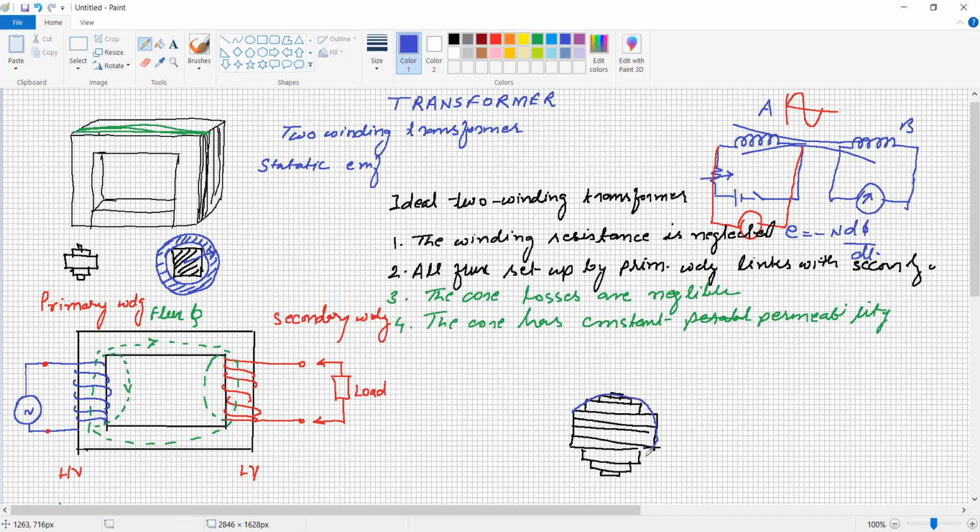Now, what is the advantage here? The mean diameter of the circle increases, whereas the net iron area, Ai, the net iron area available, will remain the same. Only the mean diameter of the winding gets reduced, which will decrease the length of the conductor. Second, because of this we will find some air gap, and here we are able to reduce the air gap over the windings.